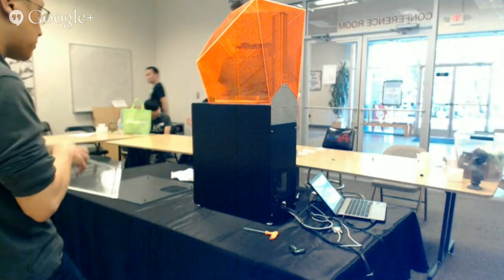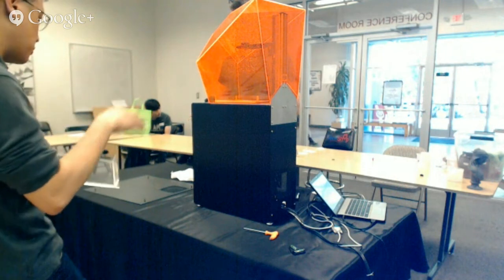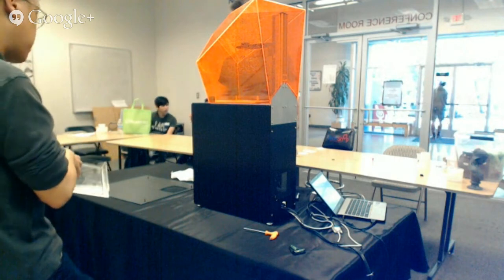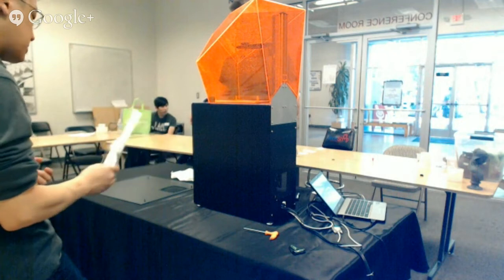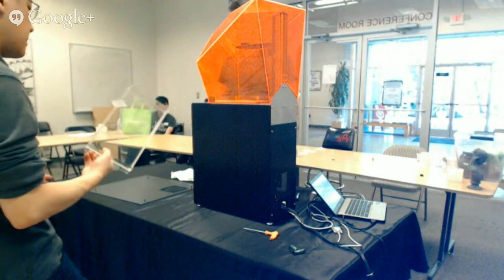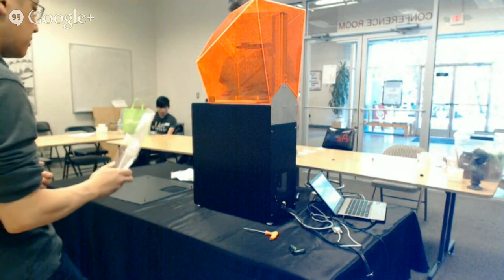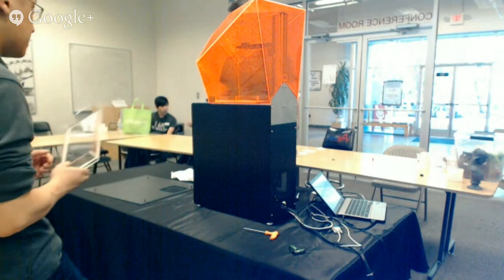It has better release properties. It also means that you can probably re-adhere new silicone and new Teflon back down onto it more easily. It also prevents the Teflon from pulling up. And the reality is that the vat is $60, and a V2 vat should last well over 100 prints. By the time I've reached 100 prints, I would just as soon buy another vat.